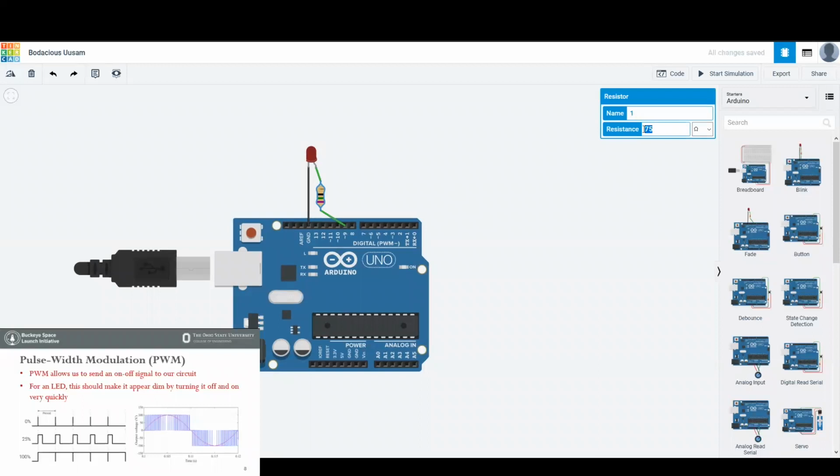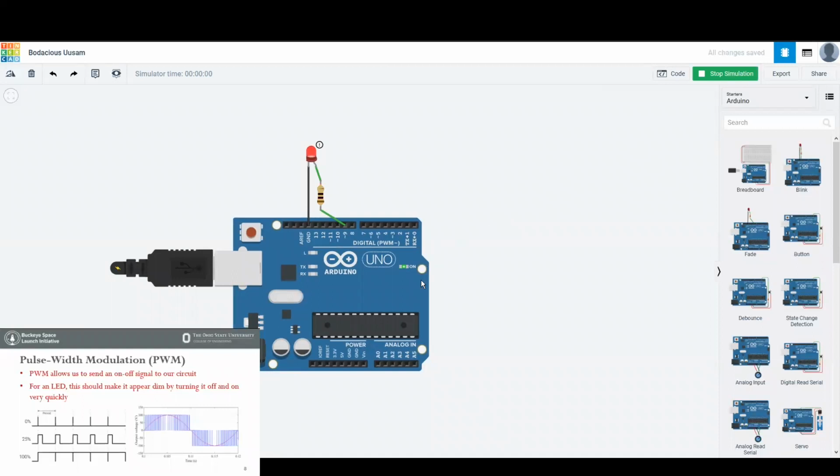And then if we go all the way to 0, actually, I don't know. I don't think this would blow up, just because I don't know if that can draw more, but we can try going all the way to 0 resistance, see what happens. Anything? It just draws more current. The Arduino doesn't seem to be giving any gripes with it, but you can see that we're drawing over 40 at some points during our cycle. That would be bad for the Arduino.